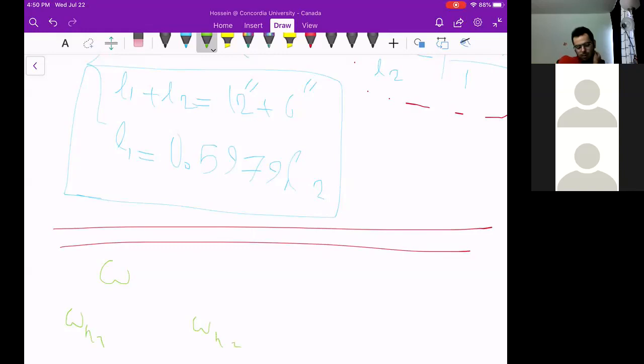From a design point of view, if the operation of the system is given to us, we have to keep the natural frequency far away from the excitation frequency in order to dramatically reduce the amplitude.